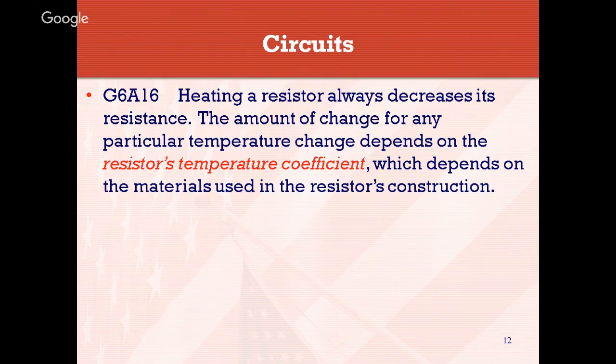If you go into a circuit and replace a resistor, you need to replace like components with like components. So you wouldn't want to take a bad half watt resistor out and replace it with a quarter watt resistor. That just wouldn't work very well, and it wouldn't work very long. So you want to make sure that you use the proper wattage of resistor and the proper value if one goes bad.